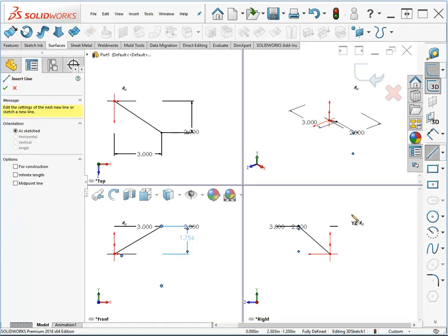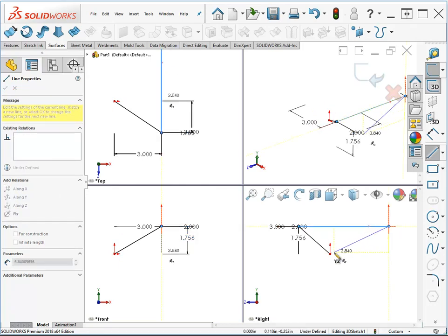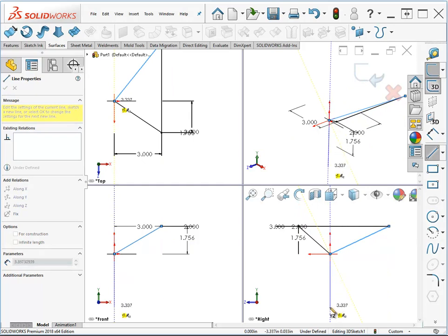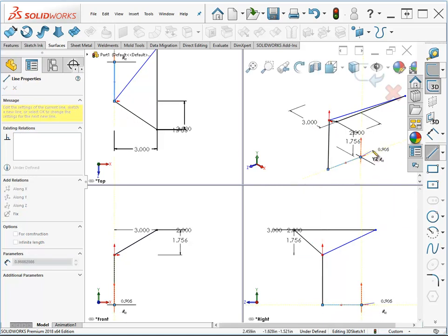So let's build something out of this 3D sketch line that we've started. We can create another line here, come back. Okay. So maybe we're creating a stand for a basketball goal. They need to be much larger than this, but we're getting the shape just about right. If you want to change the direction or the plane that it's sketching on, see, the cursor is giving you a lot of information. It's saying that it's putting this line or the second endpoint of the line on the YZ plane, on the same YZ plane as the first point was in.